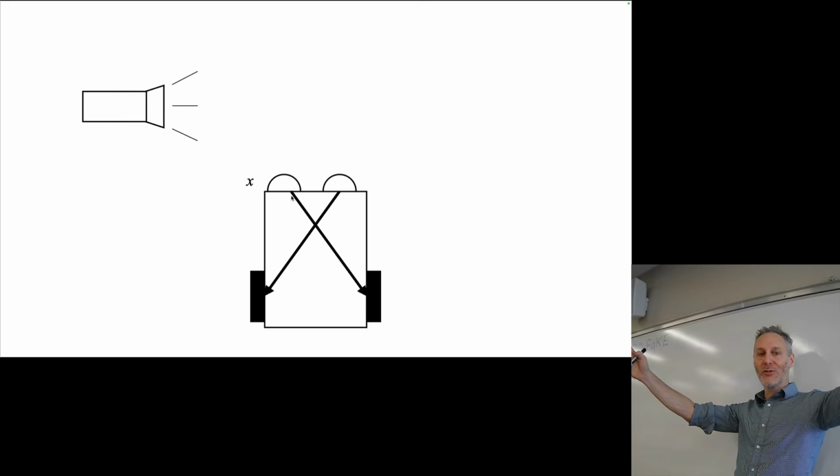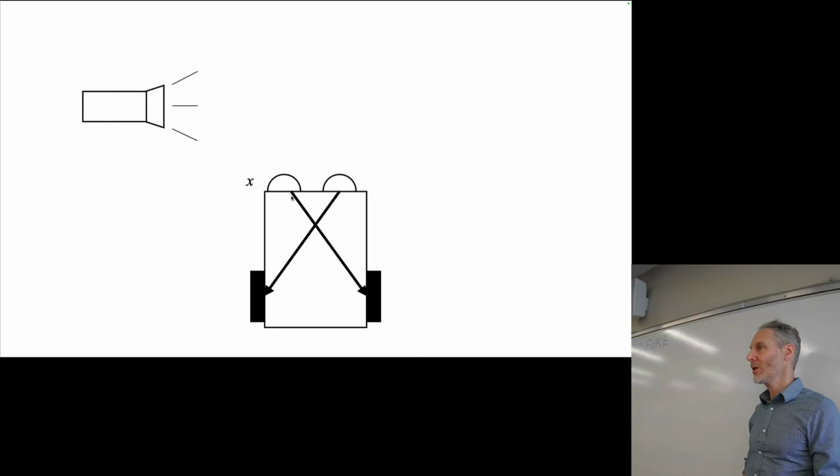what might happen if we suddenly move the left sensor further to the left? What could happen? Run your internal Braitenberg vehicle simulation. This wheel is now spinning even more strongly relative to this wheel. Sounds good in theory, but in practice, what can happen? It's just going to go in a circle, possibly. Spin. What else might happen here? Rotates, turns away from the light and stops.